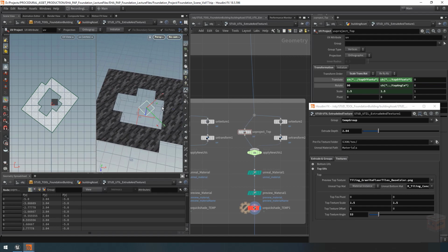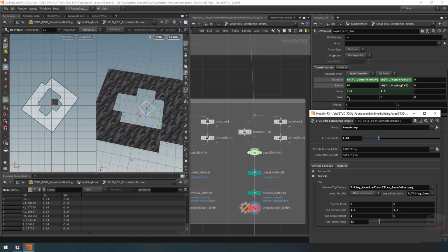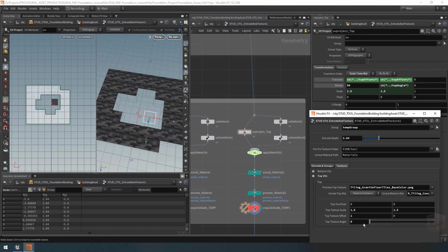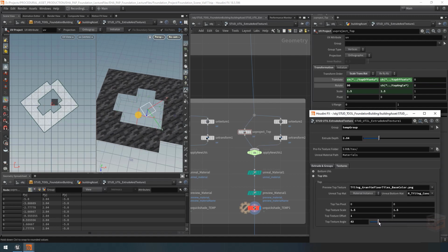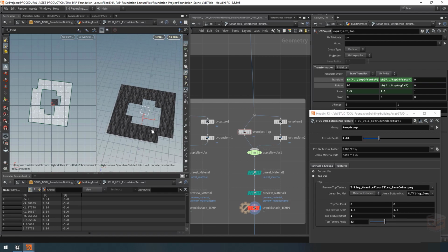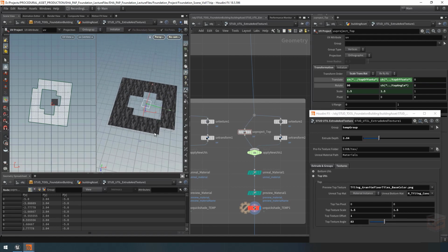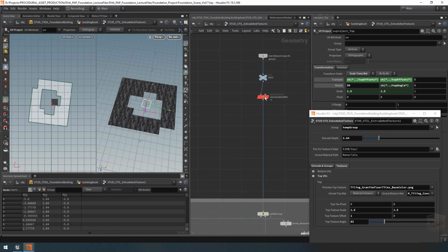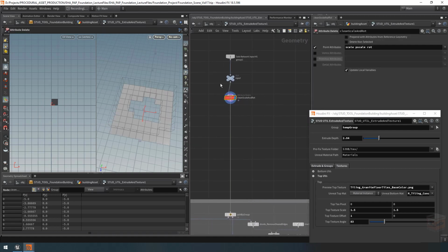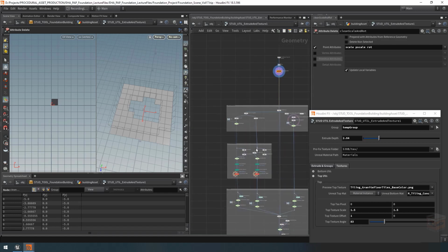Now there's one last thing that I want to deal with, and that's the pivot by which everything works here. Because right now it's set to world space, and if I rotate this thing, it's going to rotate around the world space pivot. But I might actually want to rotate this projection based on the corner of this building, like the corner of this object shape. And for that we need to move the pivot to either world space center or the corner of this building. Now, in order to get that value, I need to evaluate the shape of my model first. So let's build a system up here that does that, and then we can pull some information from there to these nodes, right?